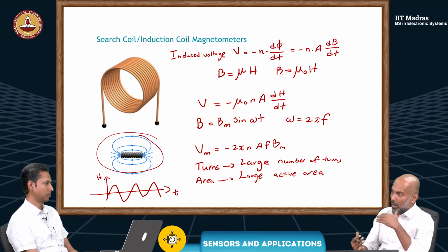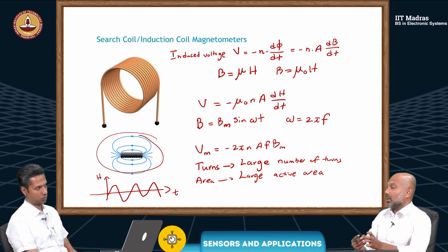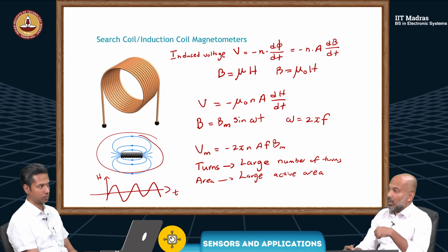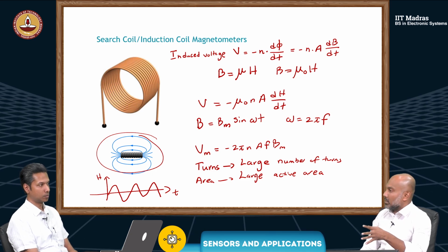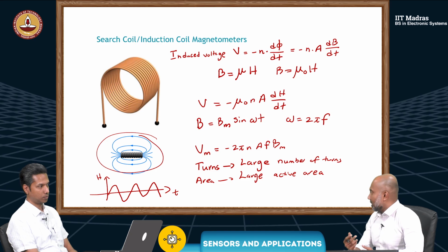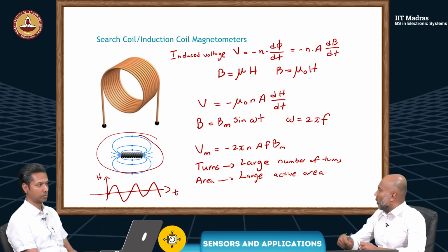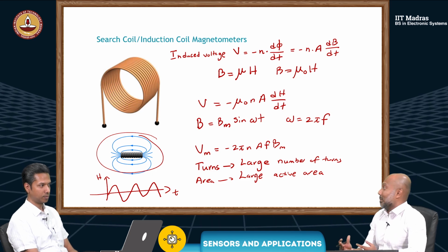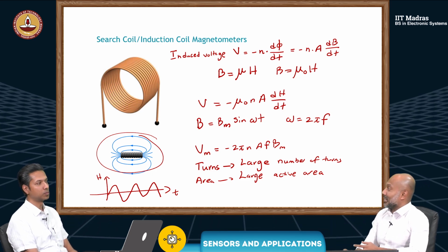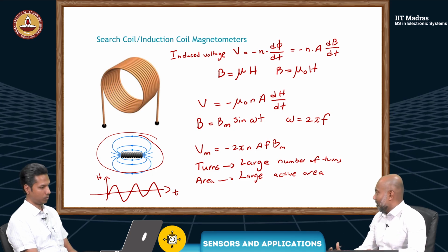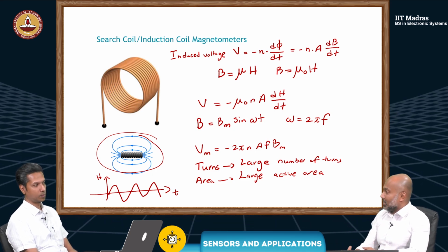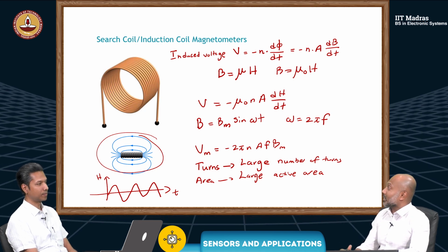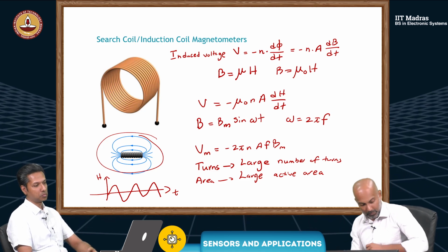One of the reasons it's used in so many applications is the wide detection range. But also, anyone can design a sensor like this, because it just requires a coil. Again, it depends on the application. For certain applications, you might want high sensitivity or high resolution. In that case, there are more things you have to consider when designing a coil like this.